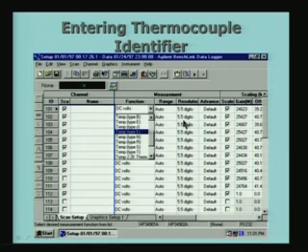That is, automatically it will determine what is the type, and it has a table of values corresponding to type K, and then it will compensate for the cold junction, and then automatically find out what is the temperature for a given input in that particular channel. So, these are all possible with the data logger. What we have tried to do is to just indicate how measurement is now done over a number of channels by using a simple data logger.